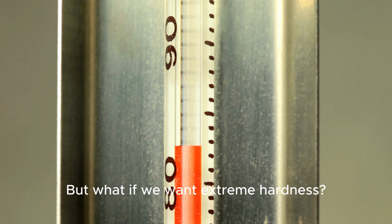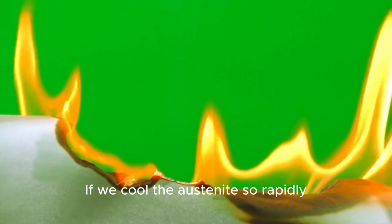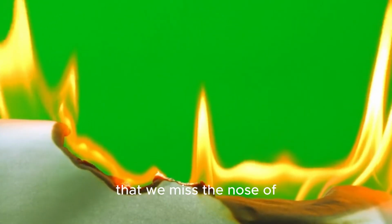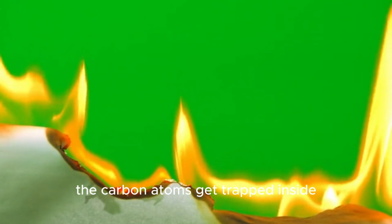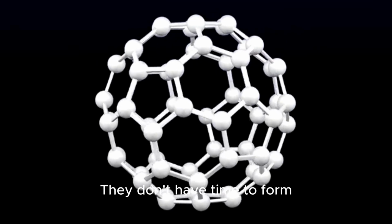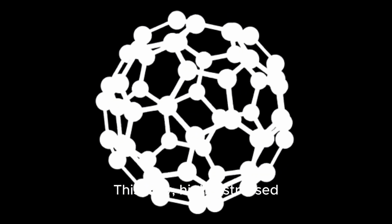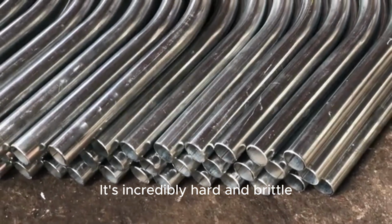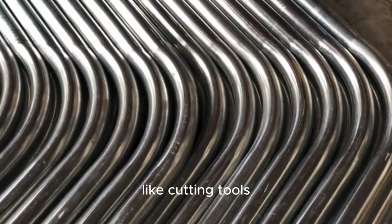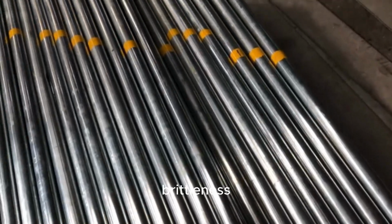But what if we want extreme hardness? This requires a very fast cool, a process known as quenching. If we cool the austenite so rapidly that we miss the nose of the TTT curve entirely, the carbon atoms get trapped inside the iron crystal structure. They don't have time to form ferrite or cementite. This new, highly stressed and distorted structure is called martensite. It's incredibly hard and brittle, which is perfect for things like cutting tools. But it often needs to be tempered or slightly reheated to reduce that brittleness.